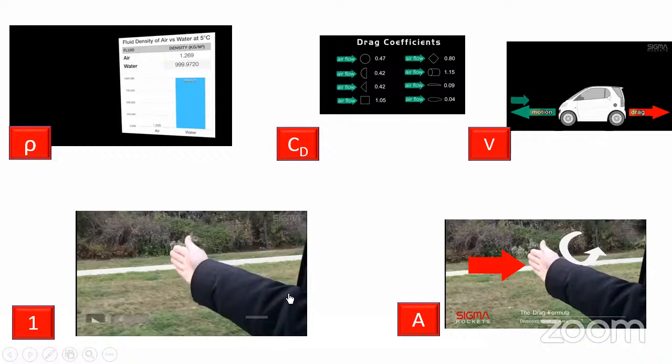Normally, the way they have designed the controller, for example, if you brake, it is not abrupt. We use something called PWM, pulse width modulation technique. Assume the pulse is 50% initially. Okay, you apply the brake, then immediately the pulse is not going to be zero. It is gradually reducing. So you can vary the smoothness. Even the designer can vary the smoothness very easily by controlling the controller.